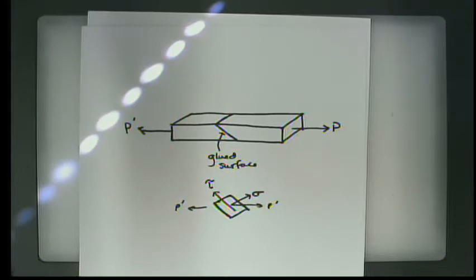And when it's orthogonal, we don't have to use the law of cosines. We can just use the Pythagorean theorem to find the actual overall state of stress. So it makes the math easier, and it also helps analyze the behavior in the material.